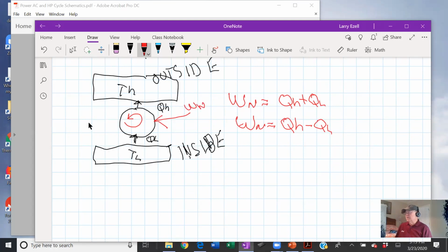And the coefficient of performance for this type of system, where you're cooling the inside, is beta. And that's equal, and I could write the absolute value if I wanted to, to what you want out, which is QC, cooling. That's called the refrigeration effect. By the way, that's the rating. You hear a unit is a 4-ton unit or a 2-ton unit.